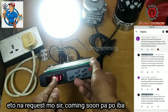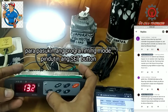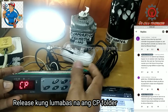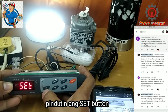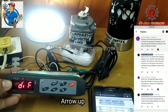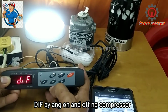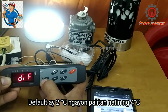Okay, compressor on. Temperature is now. Enter the programming mode. Just press the set button. Okay, now the CP appears, and let's enter that one. And I just press the set button and arrow up. Now in the differential here guys, this differential is the on-off operation of the compressor. So we're going to put a value and press set again.